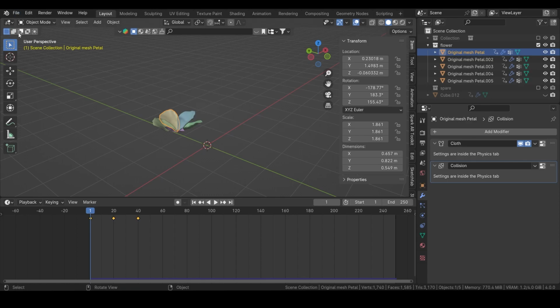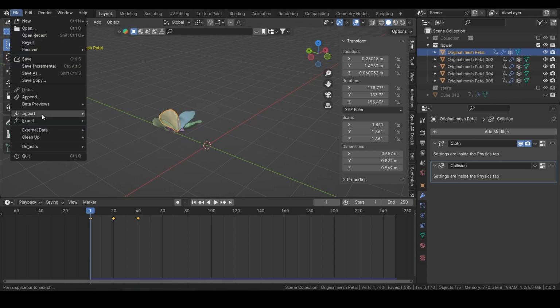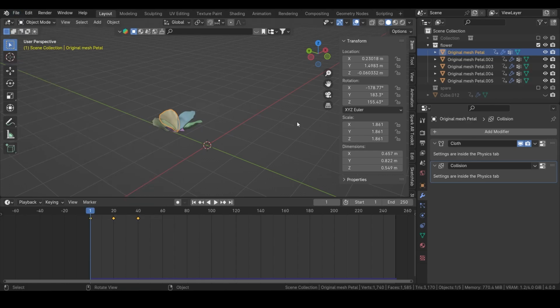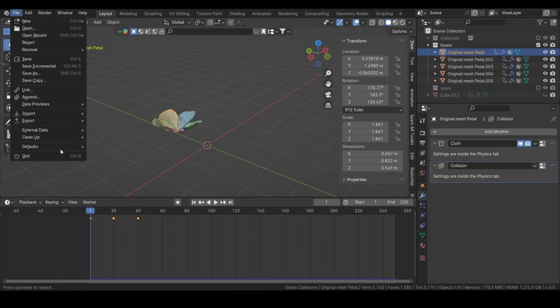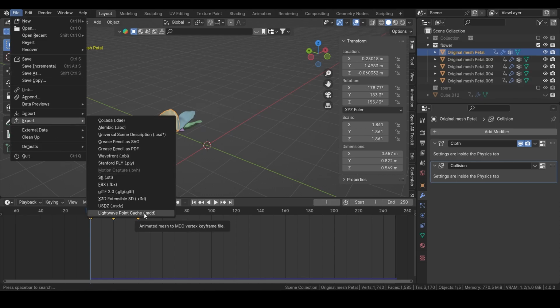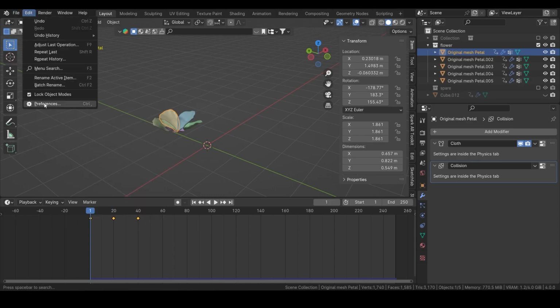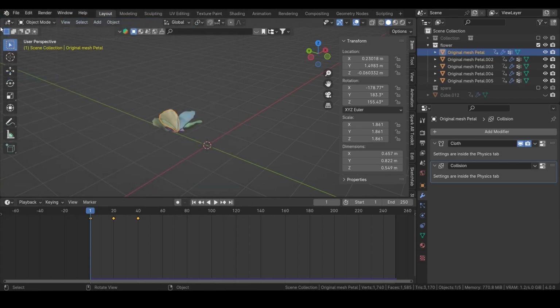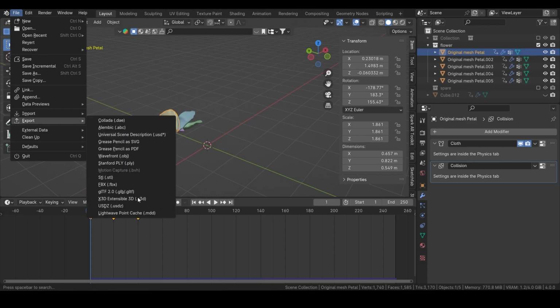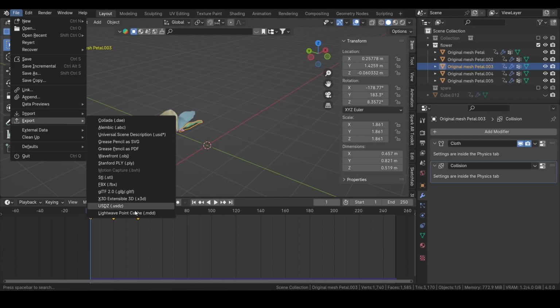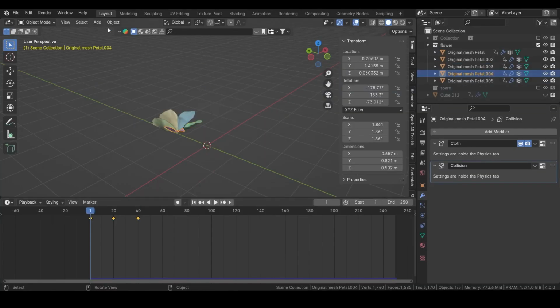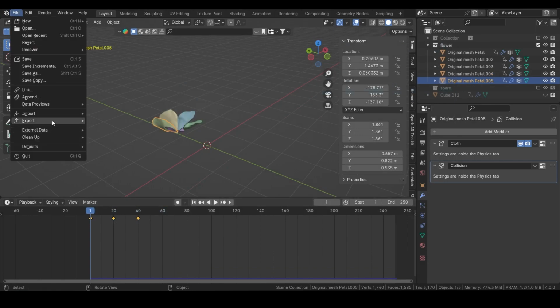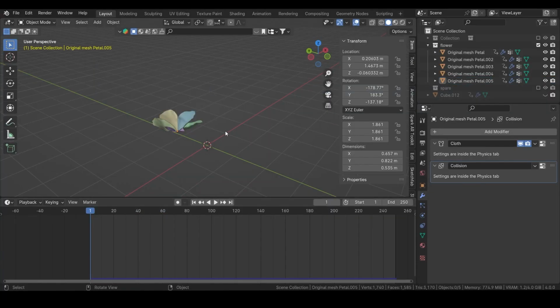these models. So select the first one, go to export lightweight point cache, and if you do not see export lightweight point cache, you go to edit, preferences, and search for new, and tick this box, go back, export lightweight point cache P1, and just go through. You can also join these things together to be able to export just one flower mesh. So now you've exported them.